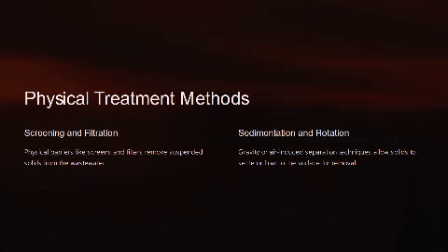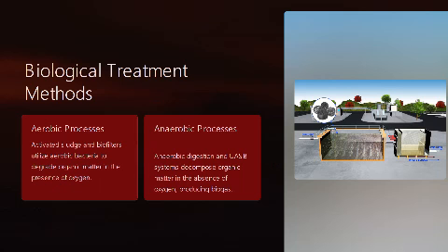Now let's look at physical treatment methods. I think we've spoken a lot about it: screening and filtration, sedimentation and flotation. Screening, you are removing big things, right? And you are filtering, you are removing suspended solids from the wastewater. Sedimentation, you want to employ the laws of physics, that is gravity. The more dense you can sediment, less dense will probably float, and then you would scoop them out in that regard.